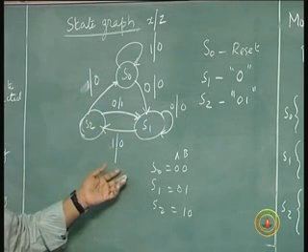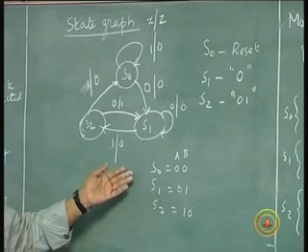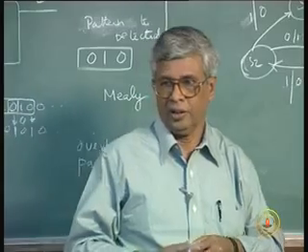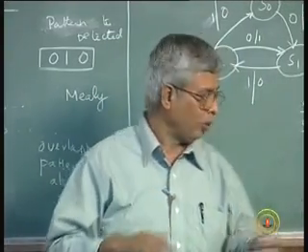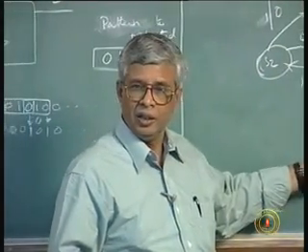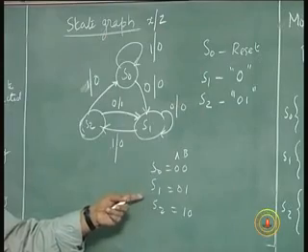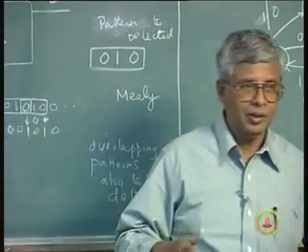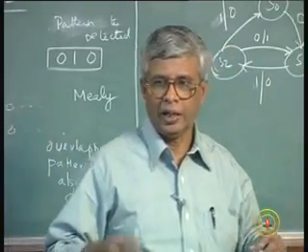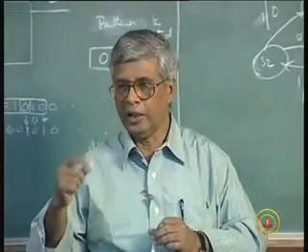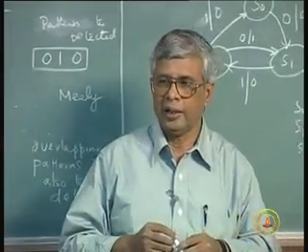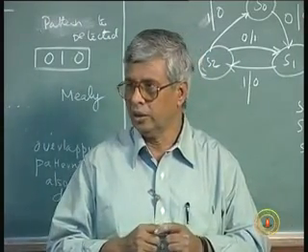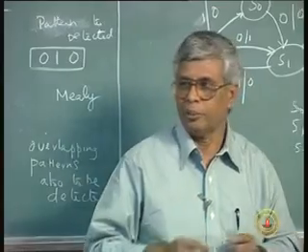And I want you to take it as an assignment to complete this state graph into a hardware design. Take this assignment, draw the state table, use JK flip-flops and get a transition table, and draw the logic diagram for the steering logic for the flip-flops as well as the output. We will see more examples in the next classes.